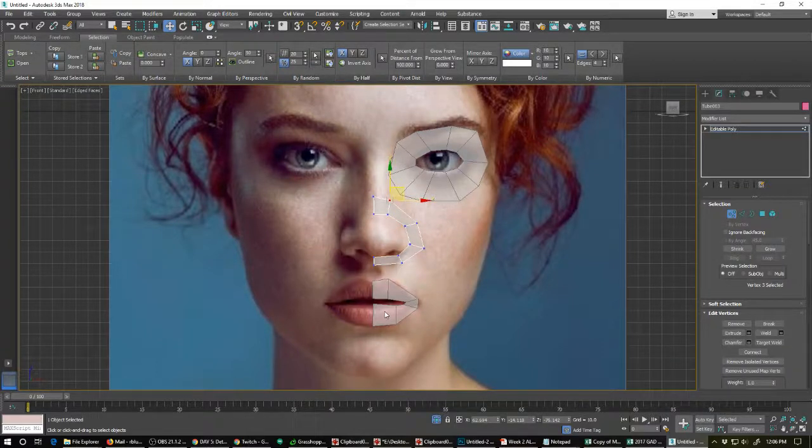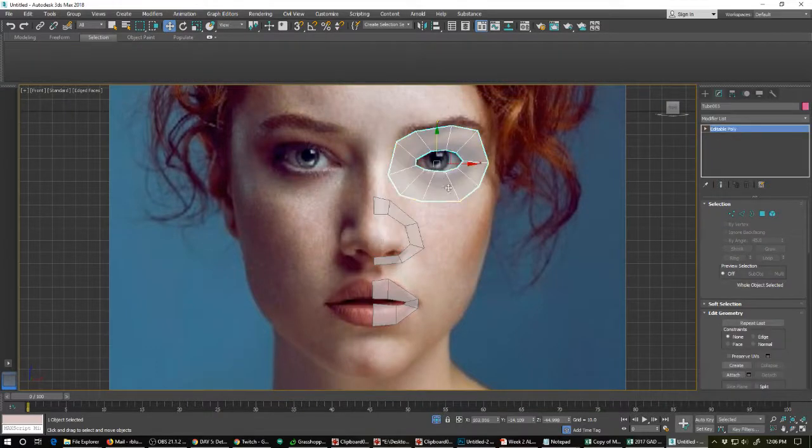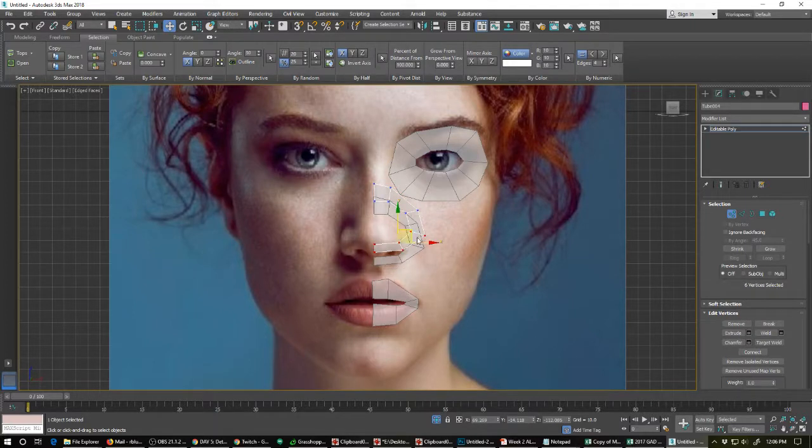And the reason it's not worth it is because in a matter of a few minutes, I can actually create what I need to do. So here's this edge loop, and I'm going to grab this edge loop here, and I'm going to actually hit OK on the copy, and I'm going to actually do this. So I'm going to bring this down here, something along the lines of like this, and then I'm going to bring this one up like so, and I'm going to bring something like that. So now I have an edge loop for the face like that.